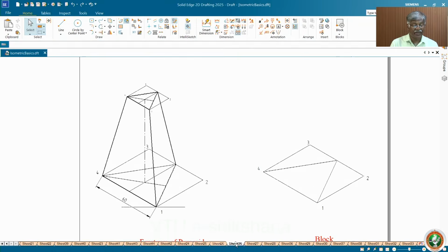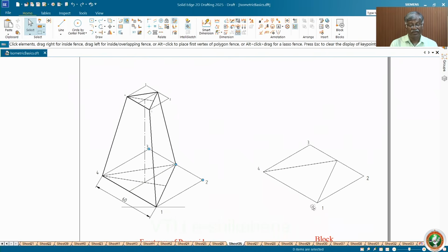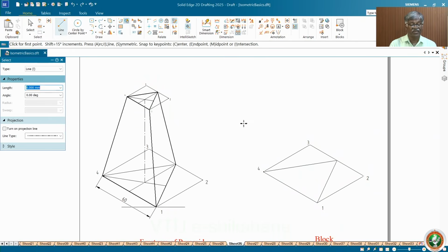pyramid, and then frustum of pyramid of given dimension, and now I am going to create what is called a block, a triangular block. Now if you draw two lines through, and this is C and B, all corners are towards you, including the corners on the two extreme lines you have drawn. So definitely from all the corners you must draw lines. Say thickness is 15 mm. Yes, 15 mm. You fix only one vertical line, 15, then draw at random some approximately 15 mm line.